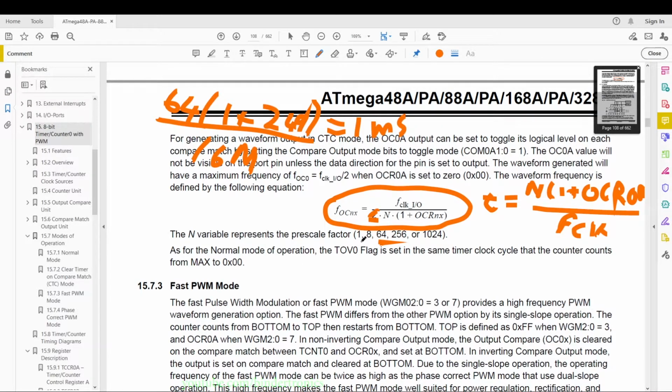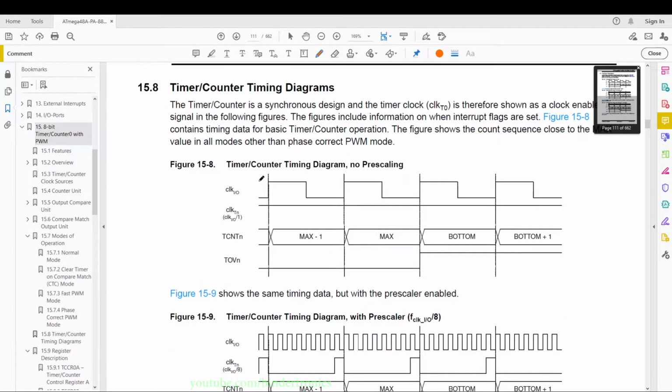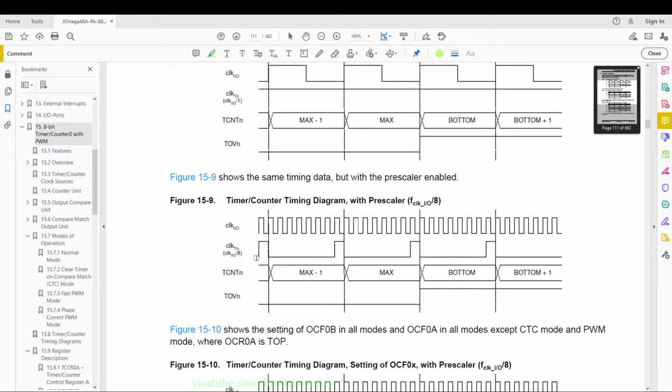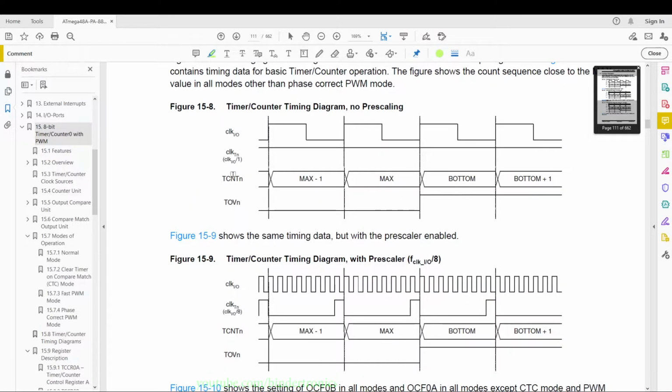All the prescaler does is it takes your clock frequency and divides it, and that's how much a single tick will be. So the timer register will increment by 1 for each oscillator tick divided by whatever your prescaler is. And then we have the timing diagrams, which is basically what I earlier said about the prescaler. You can see here a prescaler of divide by 8. Here's the clock frequency, and then every 8 cycles we add max by 1. And you can see here with a prescaler of 1 we tick on every clock cycle.